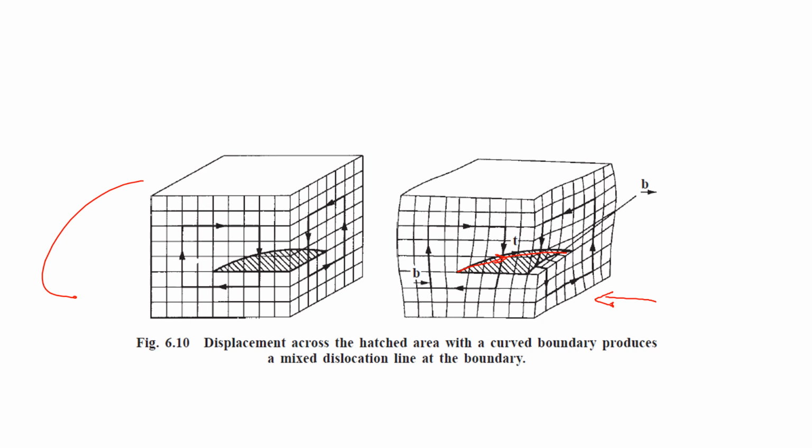So the Burgers vector here for the edge dislocation is shown in this direction, the right direction, and when seen from the right side, it is a screw dislocation, and the Burgers vector is this. See here, both are in the same direction. You can see both of these are in the same direction. Okay, the T vector goes into the plane of the paper on the front face. This is about the B vector.